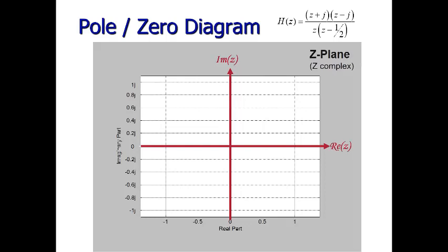The particular ones we want to denote here are which ones are roots of the numerator and denominator. So we'll also want to keep track, for reasons we'll see in a few moments, of where those poles and zeros are relative to the unit circle. The unit circle, again, was the circle of radius 1 in all directions. So it passes through -1, +1, +j, -j.